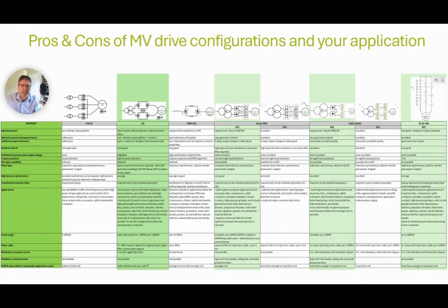And nearly finally, the redundancy in the power circuit. It helps to increase drive availability. This redundancy should allow the continuation of the process when a cell or power component fails. However, this is not possible for every kind of drive. The LCI, MMC and 2-level series Cascaded H-bridge can offer these advantages. Restoring redundancy is paramount for the drive system's availability.